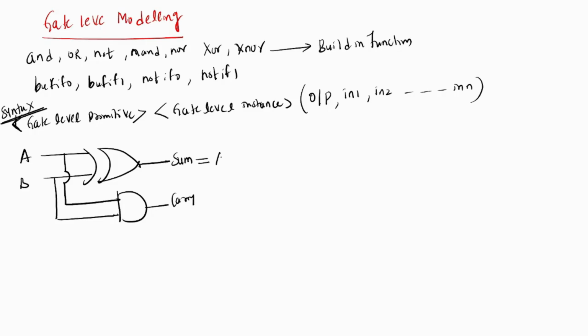Sum equal to A XOR B, and carry equal to A and B, AB.